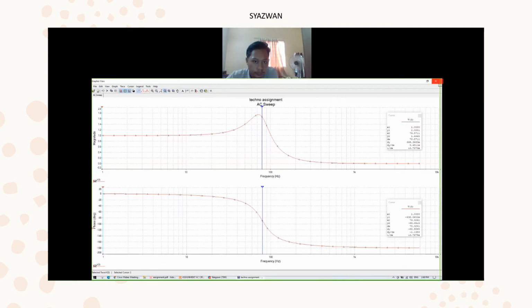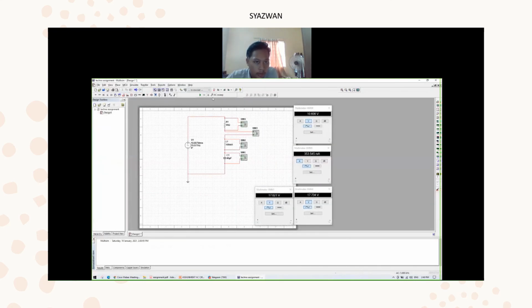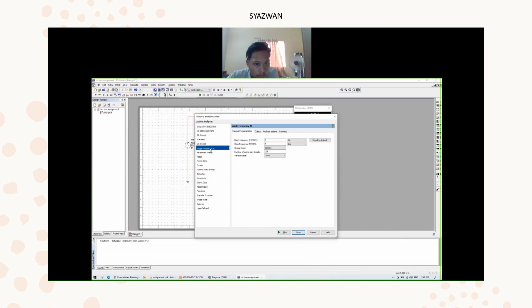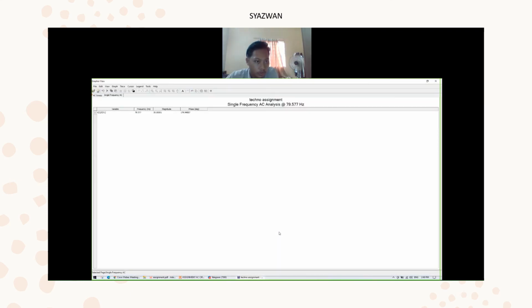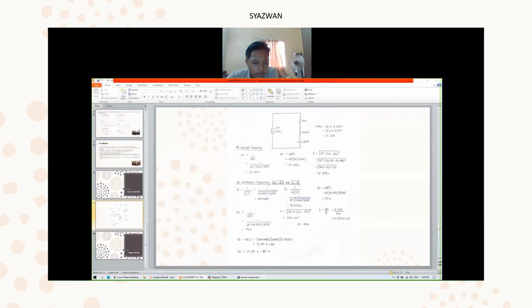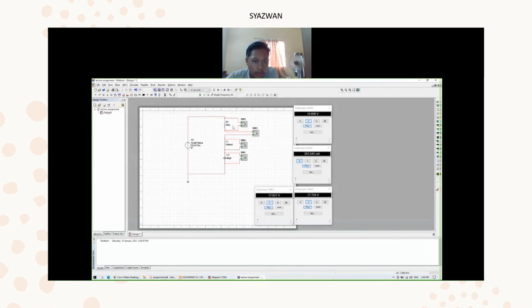And next, to prove the impedance theory is correct or not, we must click here and click single frequency AC and run. Okay, so we get here the value of magnitude. We get 30, and also the resistor we get 30. Okay, so that proves the theory of impedance is also correct. So that's all from me. Thank you.